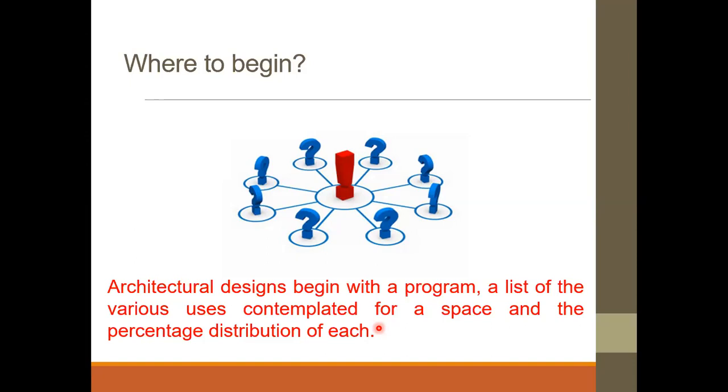You will find that the minimum size of a room should not be less than 100 square feet. This is a standard rule. So if the size of the room should not be less than 100 square feet, a residable room should have the size or percentages you will calculate as per the requirements.